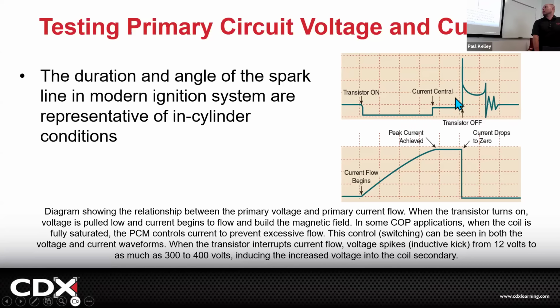It's charged, turn it off, spark it, burn it, leftover coil energy, turn it back on, charge it, have it filled up, spark it, burn time. The coil oscillations are like, hey, we're no longer burning, but there's still some energy in the coil, right? So this waveform can tell us a lot.